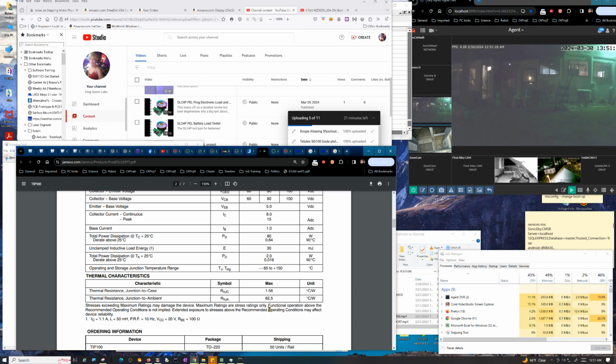Okay, so your cooling air is actually having to come laterally, from the sides. So you'd measure it as close to the circuit board as you can, probably. And that would even include if there are heat generating components mounted on the other side of the circuit board. So that's still going to contribute to your local heat for this component.